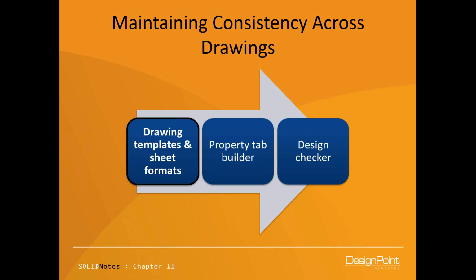Okay, so that's how you create the template, and what you can do with that is to create a standard drawing template in sheet format up front, and then distribute this to everyone working with SOLIDWORKS drawings, either through EPDM, or if there are just a couple of you, you could just email it and use that throughout the drawing creation process. So this is going to reduce the amount of time individuals are spending redoing their drawings and trying to make them look the same as other drawings, and it's going to give everyone a really consistent starting point for their drawings.